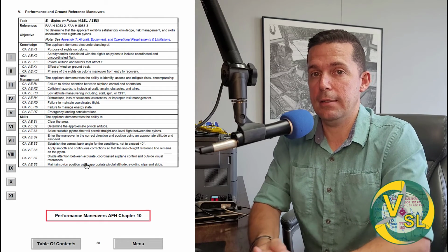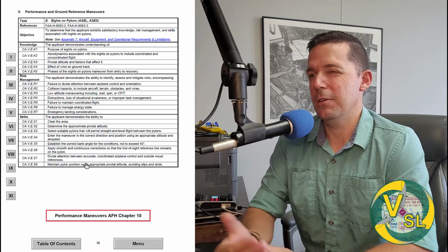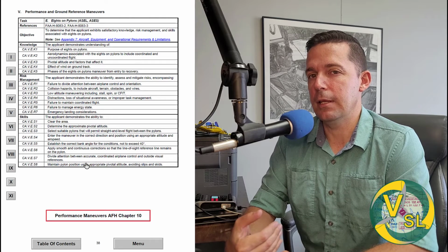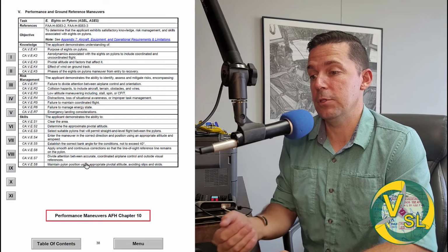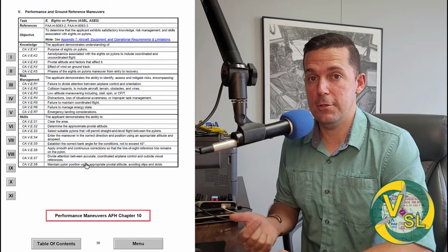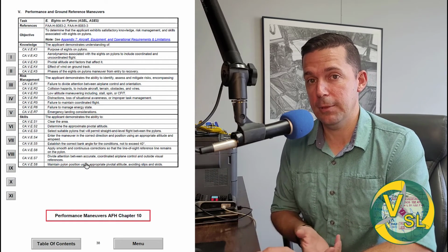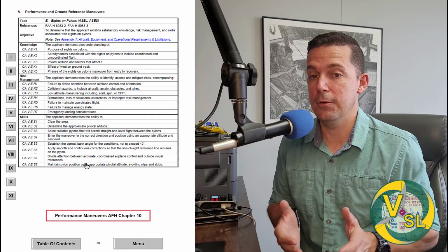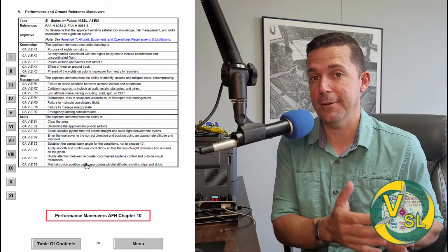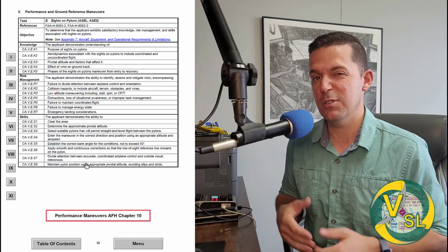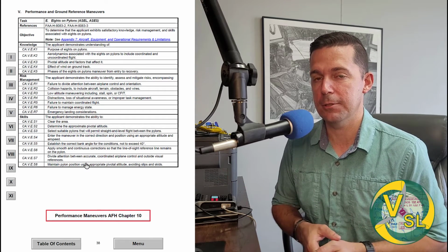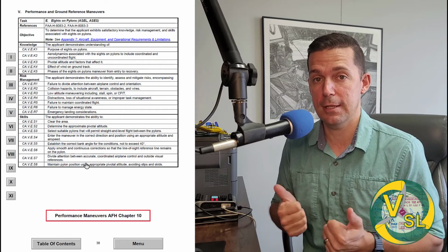It's great that you know how to calculate that equation, but you're not showing me really anything as an examiner that I'm looking for there. I'm looking for good aeronautical decision making, which means not having to do calculus in the airplane with a calculator. It's knowing to do that ahead of time and having that already figured out and written down somewhere. So when we get out to the airplane, you say, hey, my pivotal altitude's approximately 800 feet, so that's where we're going to start. Perfect. That's a good answer.